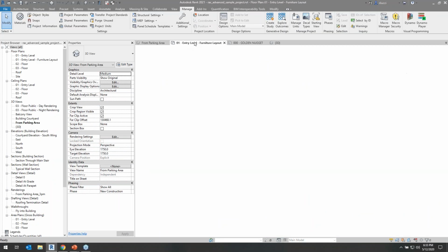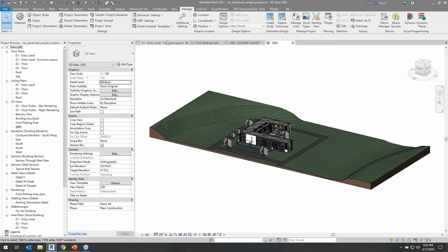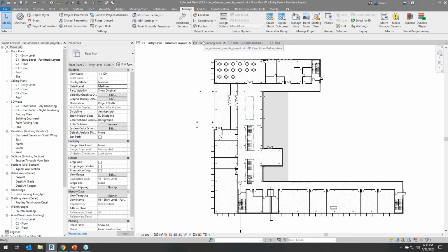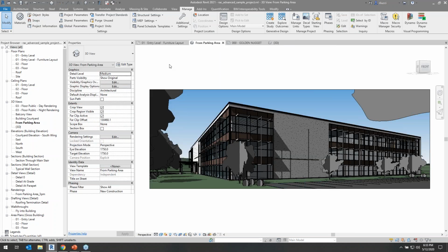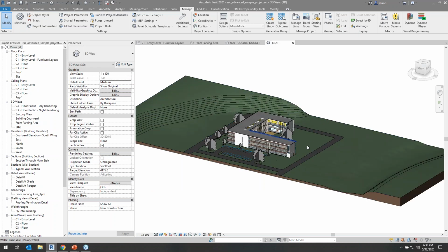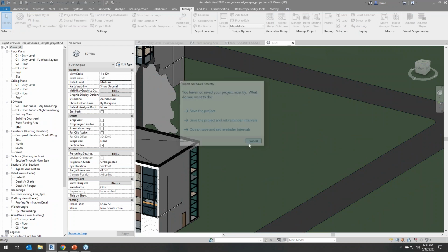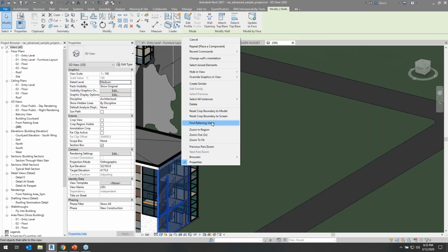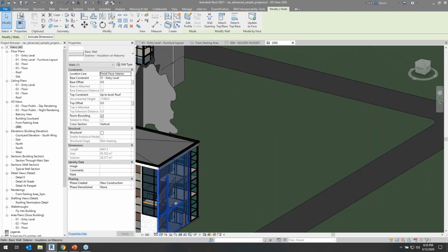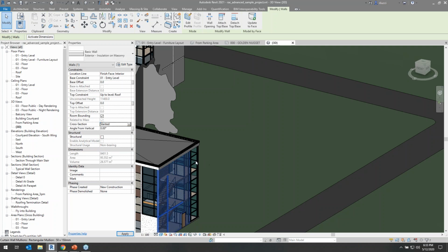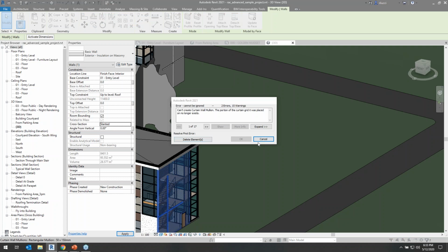So I'm going to go to this other project. Oh wow, where's my other one? I like the little house too, but oh well. So we're here. I'm just going to grab any wall, and I can do it right here. We'll see. Sure, I didn't practice this, but there's the property. Grab that wall, switch it from vertical to slanted, and then you put an angle.